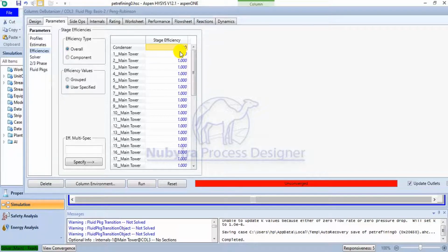But condenser, there is perfect mixing in the condenser, because it's like a vessel on its own. It's not a stage, you understand. So everything is actually condensed in the stage, you understand. And there is no mixing of two phases. It's just one phase, that is vapor phase, that is coming to the condenser, and it's condensed, you understand, to another equilibrium state, which is in liquid state, you understand. So the efficiency for the condenser and the boiler is always one, you understand.